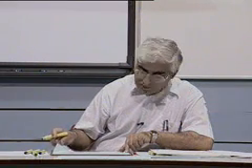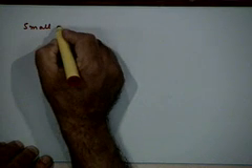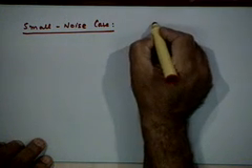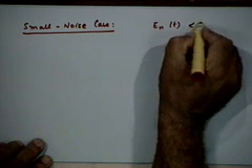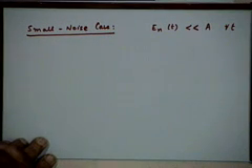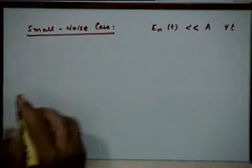Once again, to proceed further, we have to consider two situations separately: the small noise case and the large noise case. So let's quickly consider the small noise case, and then we'll look at the large noise case if time permits. We may not be able to complete it, but let's write a few expressions. So let's first consider the small noise case, defined as the situation where the noise amplitude is for all times much smaller than the carrier amplitude. That's the definition of the small noise case.